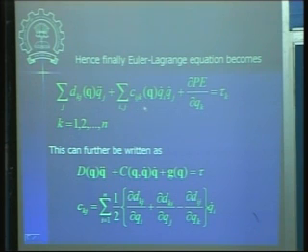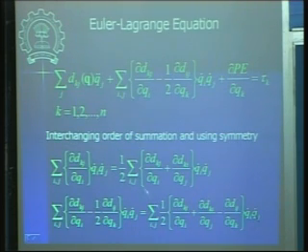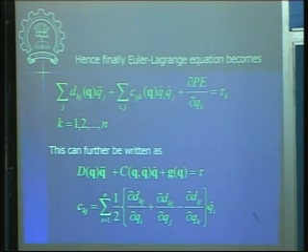Now the next term can be expressed as this summation. We have basically separated out the q dot i, q dot j terms and multiplied by some c elements, and these c elements we have just derived and they are expressed to be of this form. In the previous slide we had seen that your c elements are of this form. So the final equations of your manipulator are obtained in this form.